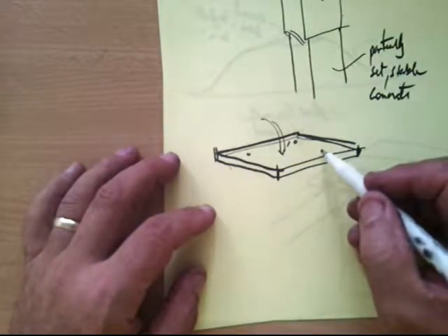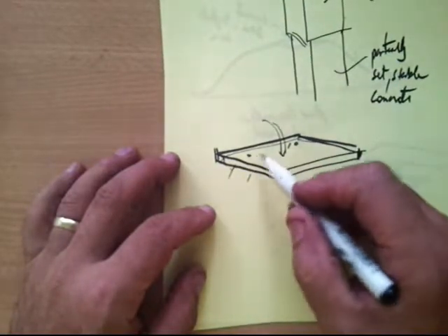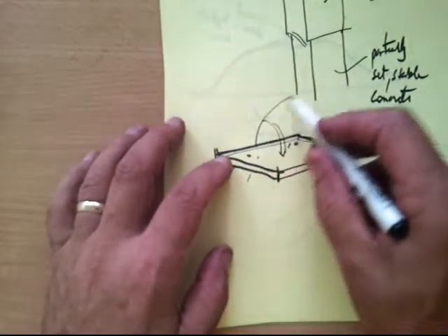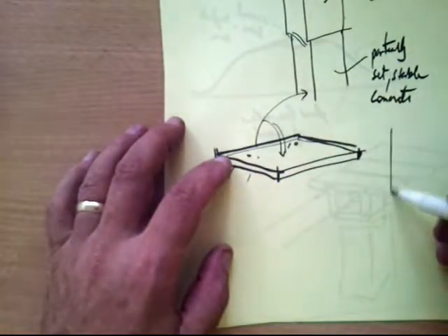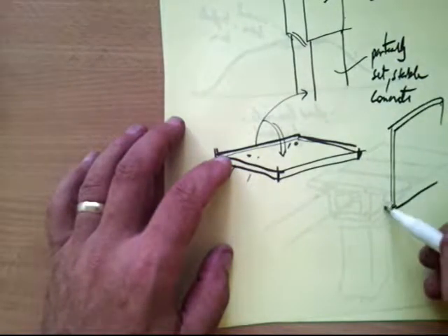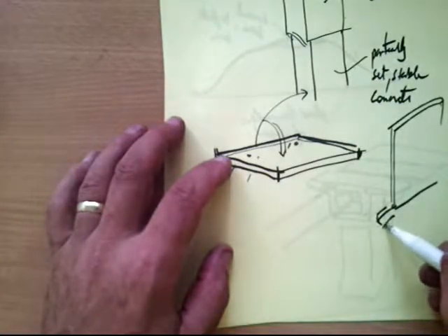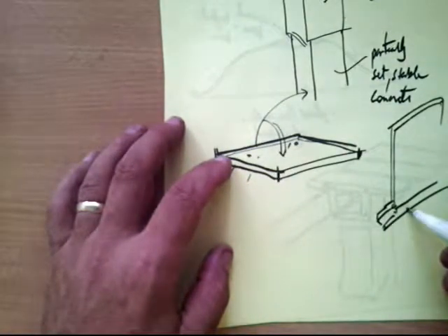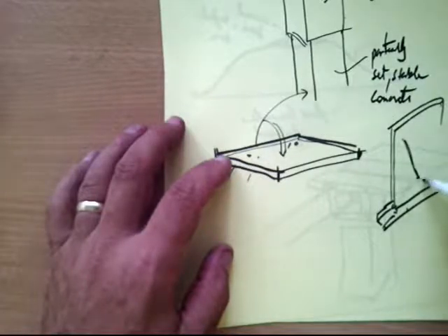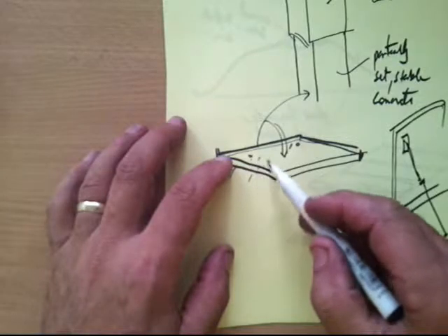That slab will have some little holes attached where it needs to be bolted and gripped and moved, and it'll be shaped accordingly. When it's set on site and the formwork is removed, the concrete can be tilted upwards like this, and it creates a vertical wall section which will fit inside a slot. Usually you'll notice there'll be some mating slots down the bottom, and the concrete will just drop into that slot.